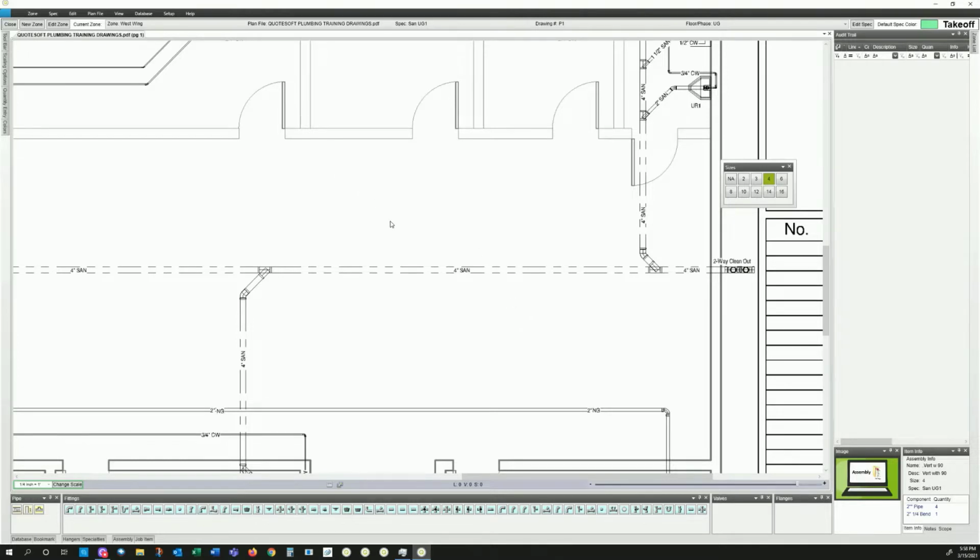And what quick keys are is I have keys set up on my keyboard. If you look at that picture down the bottom right, as I'm changing keys here, it's going to be changing fittings. And you take off 20% of the fittings 80% of the time, and so we want to make sure that we capture your most common fittings on here. And I'll show you how easy it is for me to do an underground takeoff with this sort of setup.